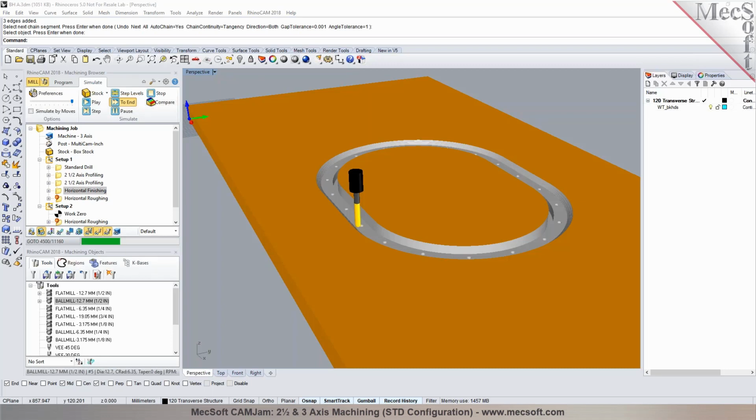You can see the power of the knowledge base here, so I didn't have to go through a whole bunch of programming. And the two parts are totally different. They're not even identical or have anything in common, right? Right. So we were able to apply the same toolpaths, like the drilling and the finishing operations, to this. Yeah, that was super awesome. But you have to save the knowledge base from the last one. Yeah, you can even open the file and save it at a later point in time too.